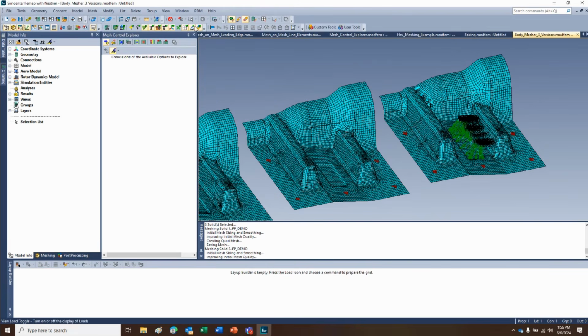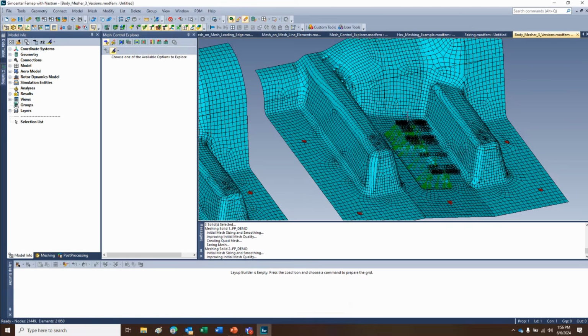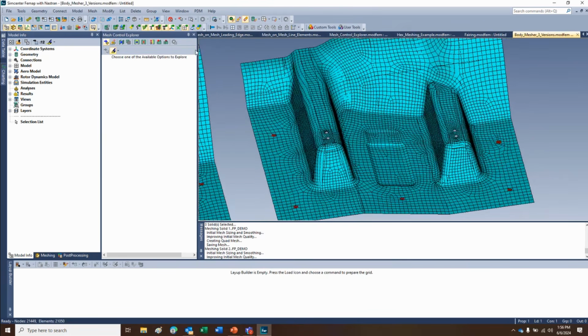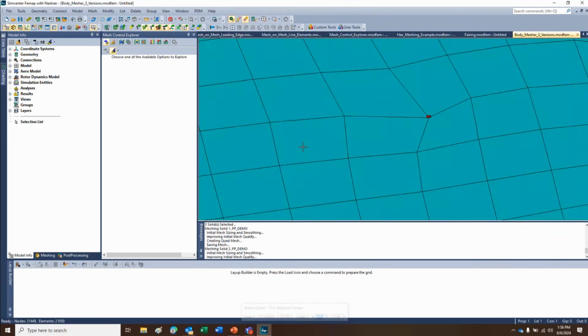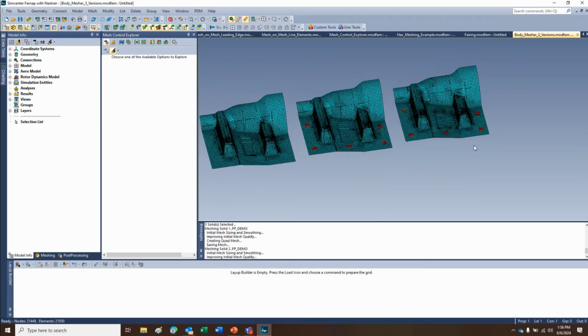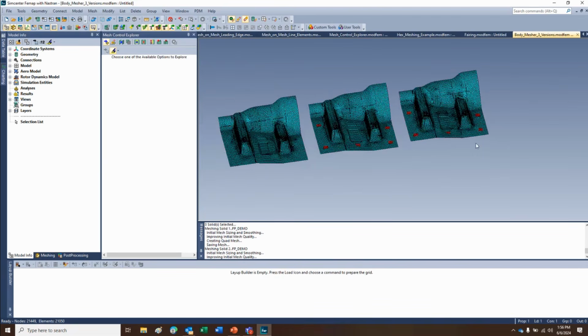But then you can see over here, if I turn off my loads and boundary conditions, you can see that it followed there because it knew it needed to, because those were loaded and those were constrained, and then it follows the mesh points. And you can combine using the body mesher and then using the mesh on mesh. You can do whatever you want in terms of that.